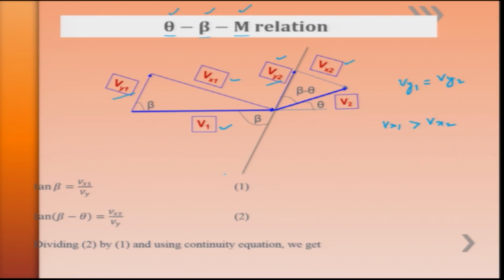Now, from this schematic diagram, using trigonometry, we can write down that the shock is making an angle beta here, and the flow deflection, that is, the flow coming out of this shock wave, is making an angle theta, which is nothing but the wedge angle or deflection angle. Wedge angle means the surface is turning into the flow, and since the flow has to be parallel to the surface, that inclination of the surface is theta, and hence I am representing the deflection angle as theta.